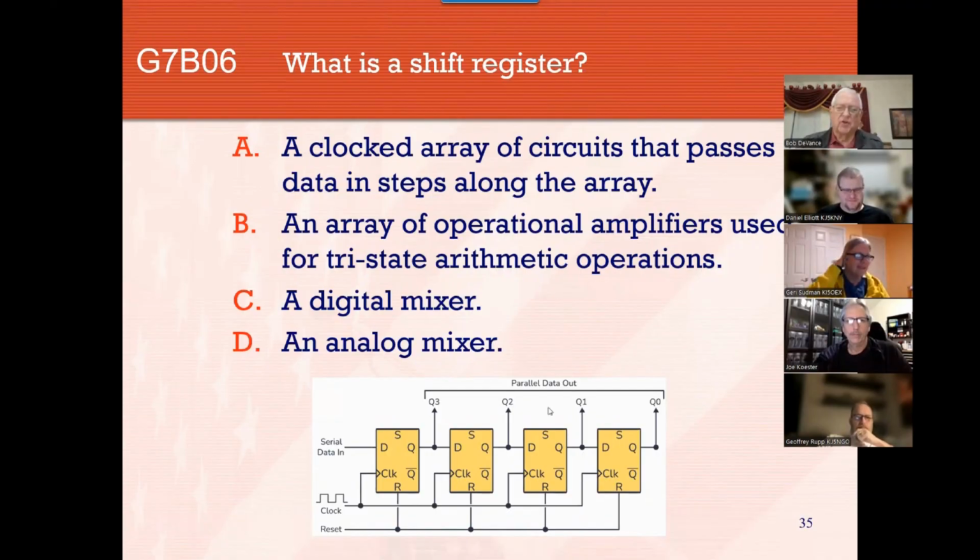And this is a shift register down at the bottom. We've not talked about flip-flops and digital components to speak of. A flip-flop is an electronic circuit that you put a signal into, and it will hold a particular state, like a 1 or a 0, until you change it by some means. So we're showing here 4 flip-flops. We're putting a signal in on the data input, and that signal sits there, rests on that data input, be either a high or a low in digital logic. And then we come in with a clock signal right there.